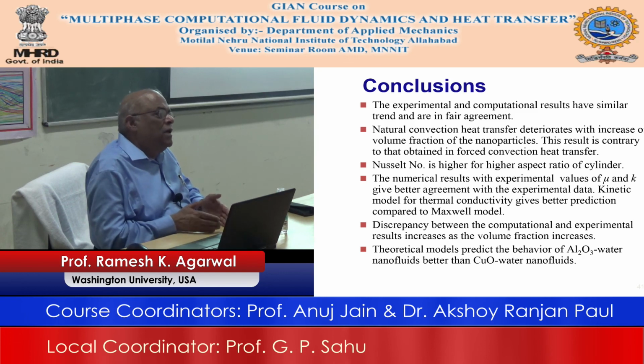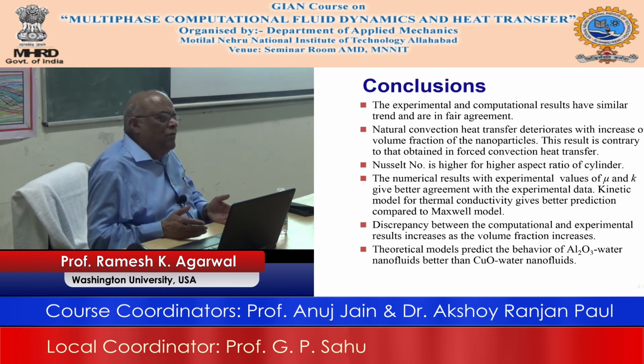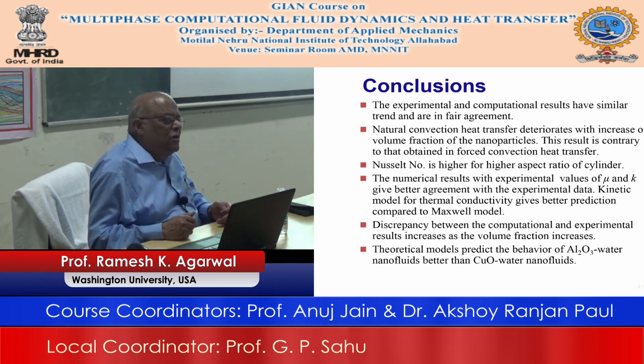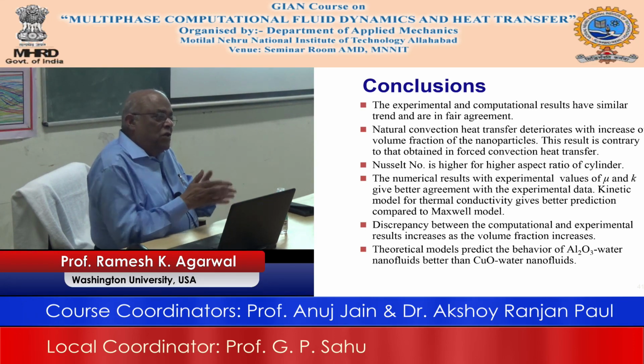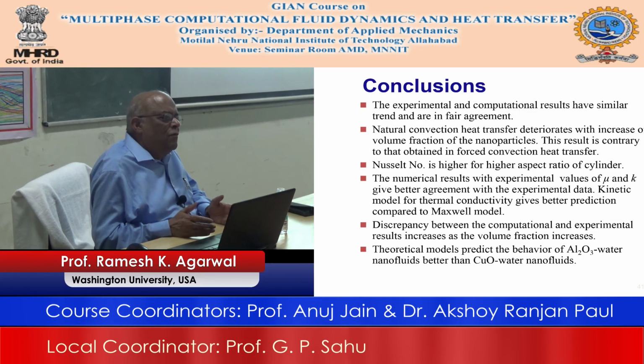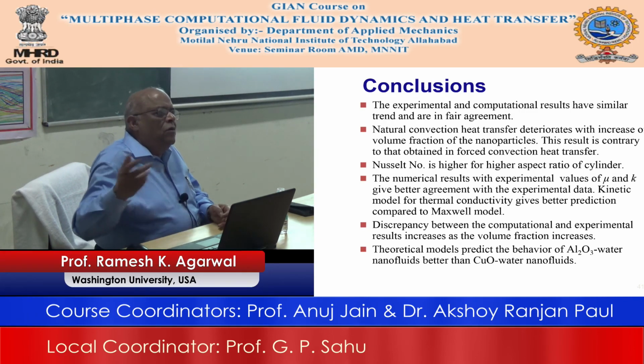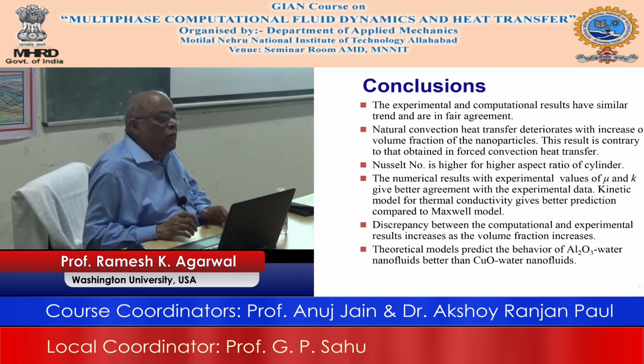But if it is not slipping, eventually what will happen? If it is a laminar flow, it will become parabolic. If it is turbulent flow, then what would happen? Now, flat is okay, but what is the name? The 1/7th power law, right? But if it is slipping, even in a laminar flow, it will keep on slipping, and it will keep on increasing this slip. So if you are not taking that physical effect correctly in your modeling, the fluid is not going to help you.